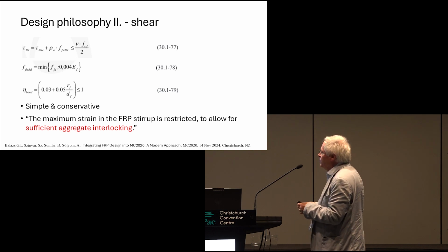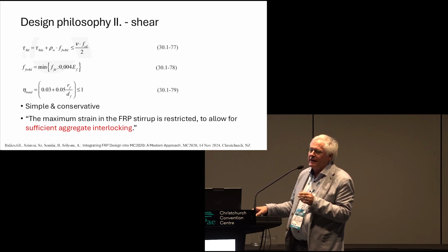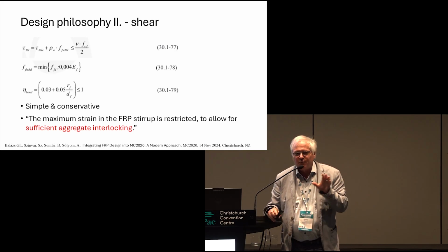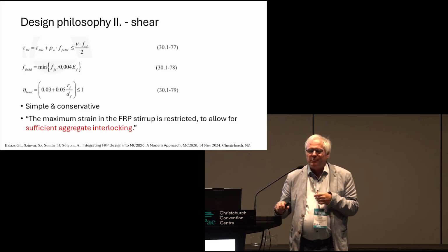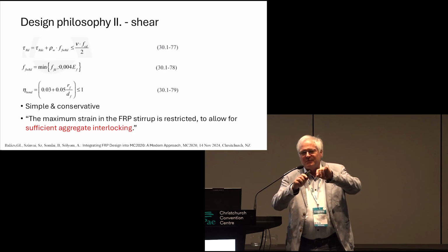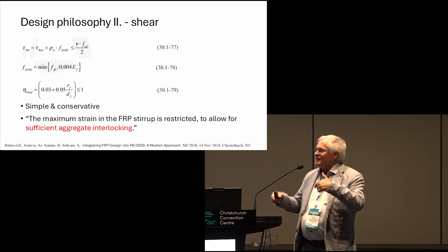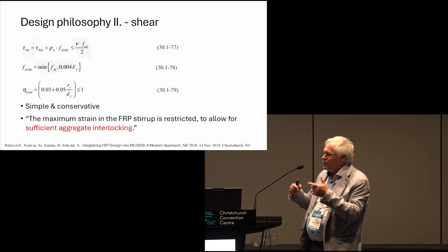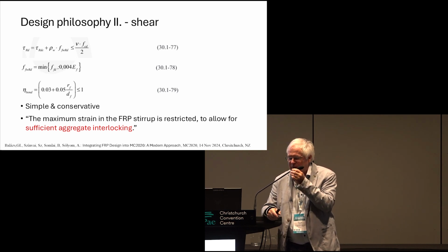There are further aspects which we could discuss. For example, the shear reinforcement is normally bent. This word is not quite good for those who learned English. We are not speaking about bending like steel bars, where you make the bending after the production of the steel. In the case of FRP stirrups, the bend is produced before hardening the matrix of FRP.